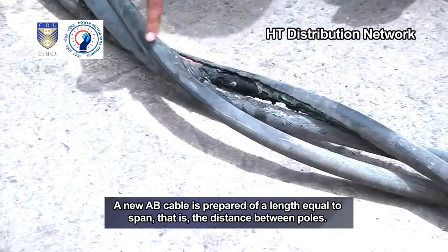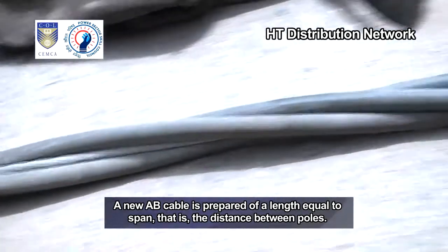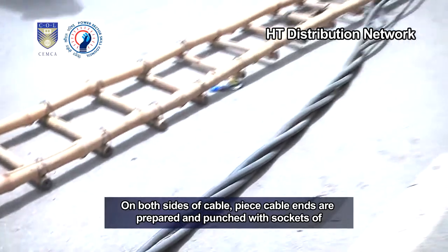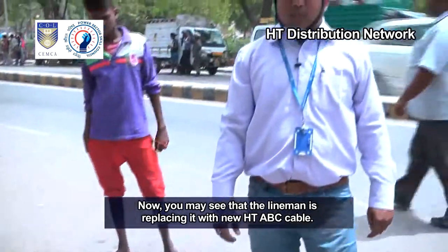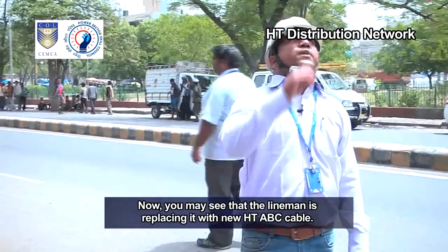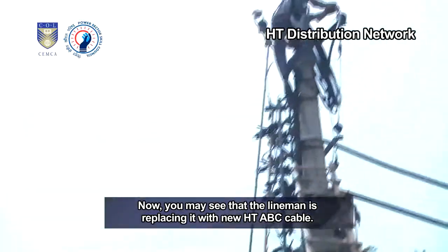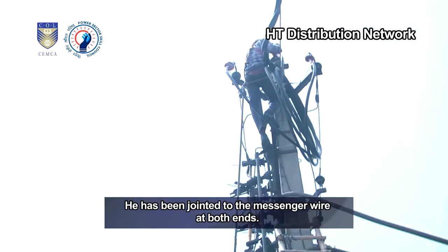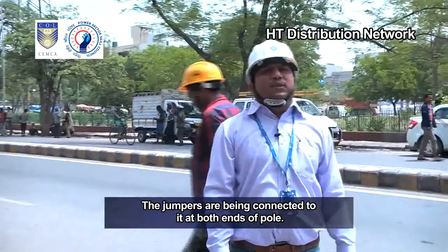A new AB cable is prepared of a length equal to the span, that is, the distance between poles. On both sides of the cable, cable ends are prepared and punched with sockets of correct rating. Now, you may see that the lineman is replacing it with the new HT ABC cable. It has been jointed to the messenger wire at both ends. The jumpers are connected to it at both ends of the pole.